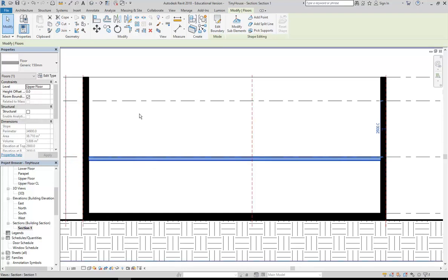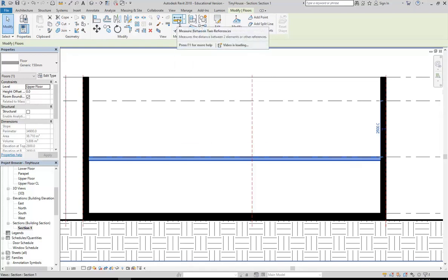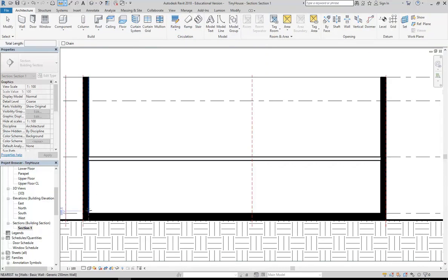It's quite a narrow space. So there is an option to make it a bit narrower, but you will still need a ceiling below that. So before I go back to the floor, I'll measure that distance using the measuring tool up here from this floor up to the one above. And you can see it's already down to 2350, which is below the minimum ceiling height, 2400.